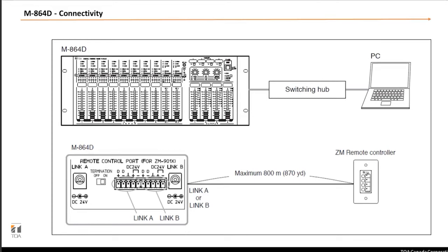Over the years, we did have some people utilizing non-shielded cable, and some problems were occurring with a non-shielded category cable, Cat5 or more. I mean, it's not important to use really the latest category cable, but it has to be shielded.